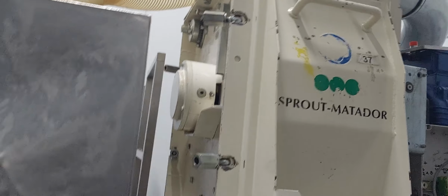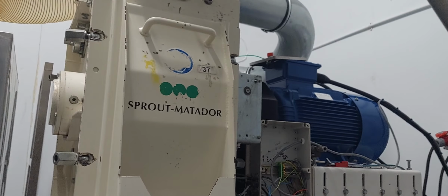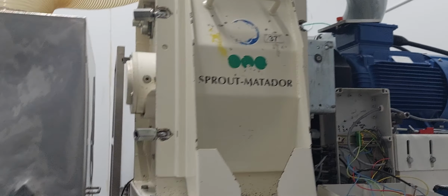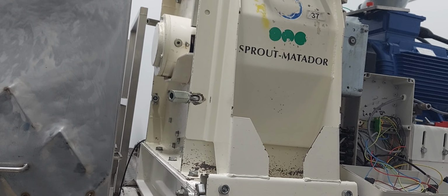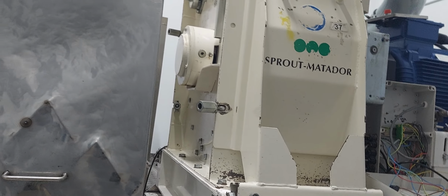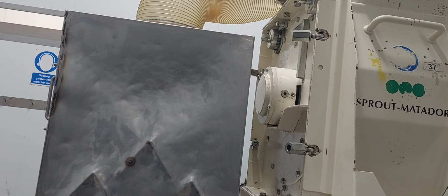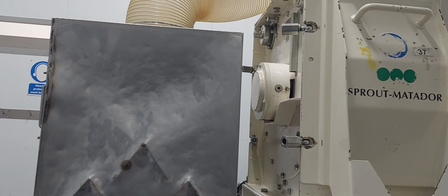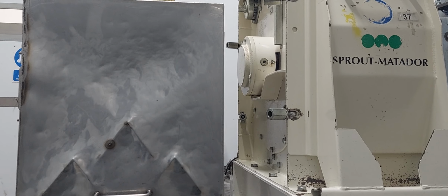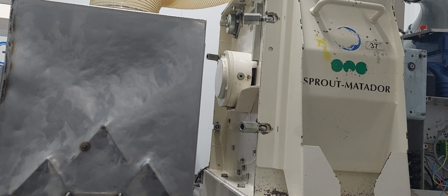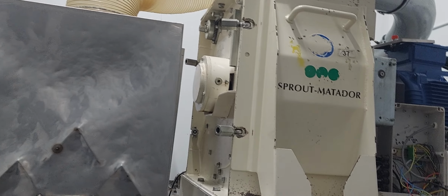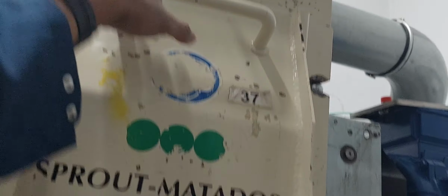the safety system. What the client wants in this case is that when this machine has been switched off, because I have replaced the control system of this panel, the client doesn't want the door to open even when you turn it off. He wants to spend some time, maybe 5 minutes, so that the inertial movement of the hammers will stop before you can be able to open this door.